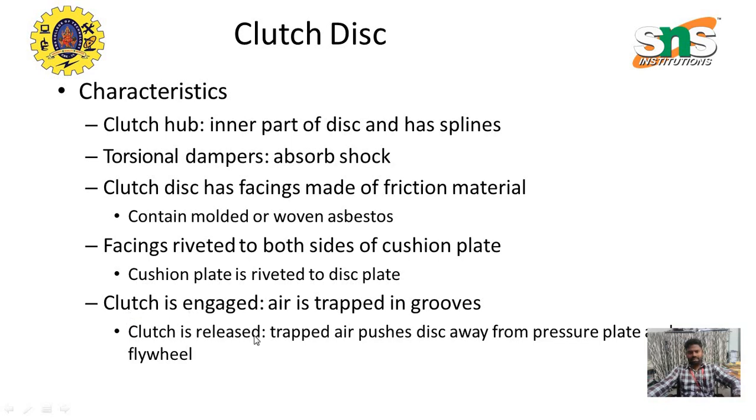When the clutch is engaged, the air is trapped in the groove. While the clutch is released, the trapped air pushes the disc away from the pressure plate and flywheel. So while the clutch pedal is released, it removes the contact between the pressure plate and the flywheel.